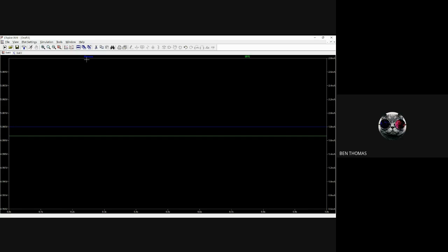You can see, right, V, and in the bracket there is a result. If more than one voltage is there, like in this only one is there, but I just added one label only. But if I want to find the voltage at more than one place, then I can name all the different ones, like V in, V out, VCC, V emitter voltage, anything I want I can label, and I can find all this in the single graph. According to the color I can know which is which. Like V result is blue, and what is the voltage? 5 volt. I can easily find it from the single graph itself.